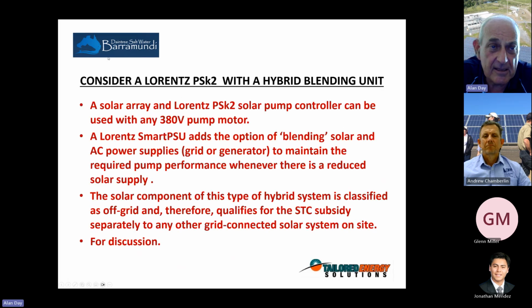And then the other thing that I spoke to Mark Hober about at the time, we are a Lorentz pumping agent, and Lorentz have some just outstanding equipment these days and new innovations. So rather than a standard VFD for this, you could actually install what's called a Lorentz PSK2 hybrid blending unit, which means that when the time is right, you could add solar to the system.